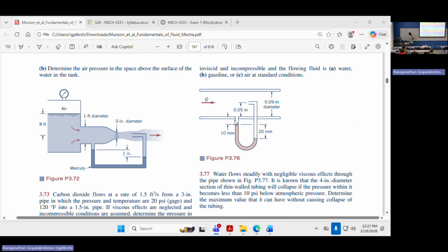Okay, so we are asked to calculate Q. Don't be sidetracked by that. You are asked for Q, you are told the diameter of the cross section area. It means they are really asking you to calculate the velocity and then multiply by the cross section area to get the flow rate. So it's a velocity calculation problem. It's a classic use of a pitot tube for velocity measurement.